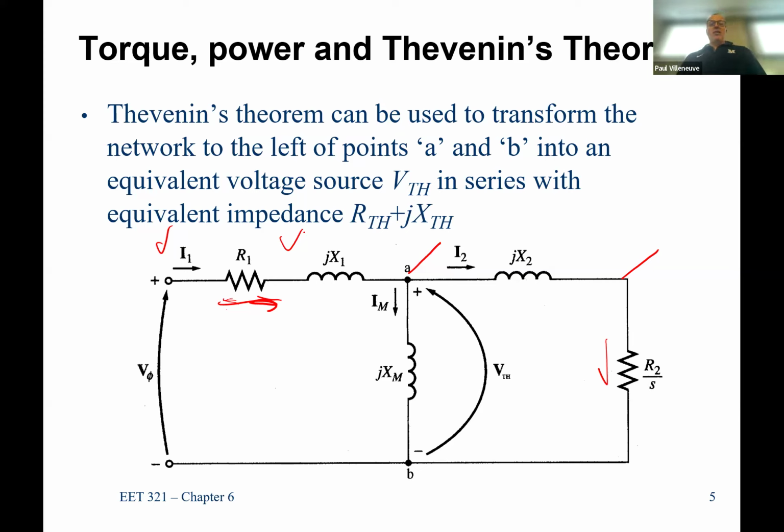All right, so now we're going to modify things a little bit. This is a modification to simplify our analysis, because what we're trying to look at is how we get power to move the system. In particular, how do we get power output relative to the change in the speed of operation, so we can come up with the torque versus speed characteristics. So the first thing we're going to do is look at an equivalent circuit. We want to transform this into a Thevenin equivalent.